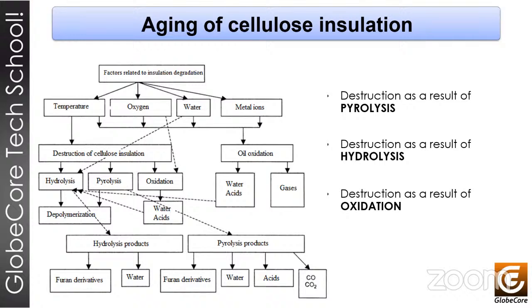In such a case, indirect methods should play an important role in order to accumulate sufficient data to assess the state of the insulation. When calculating insulation wear, currently applied standards do not take into account such operation parameters as the moisture content of solid insulation, the contents of soluble acid, oxygen, and aging products in the oil.